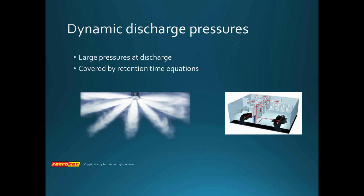What we discovered with most of the inerts is that almost all of the agent that is put into the room stays in the room, because during the entire discharge the pressure is going down, down, down, and only when we get to the point where we have the nitrogen blowing down from the tank do we start to get a small positive pressure spike.